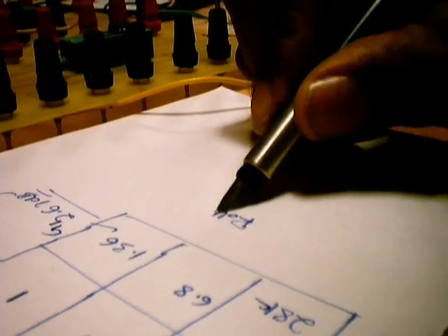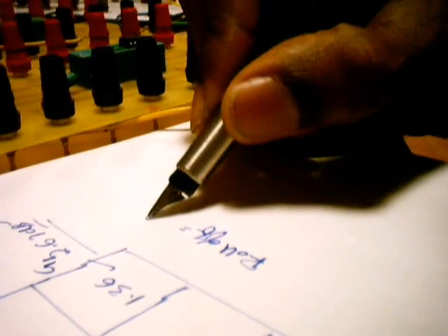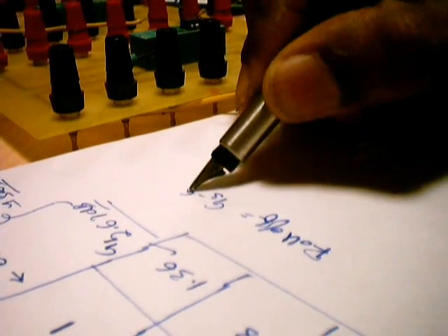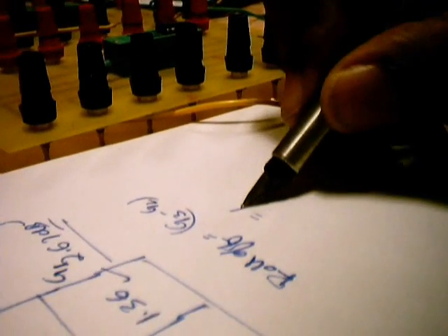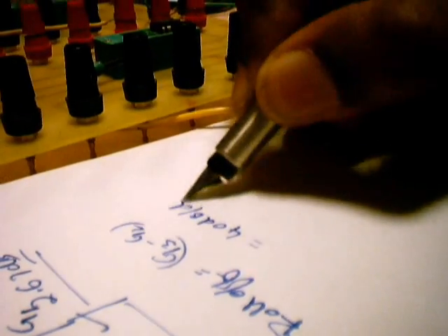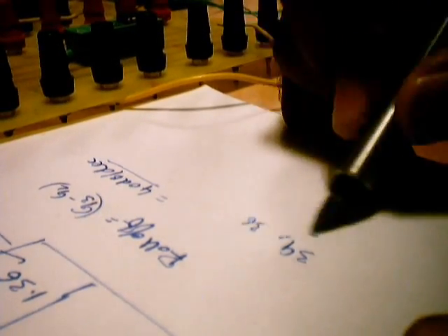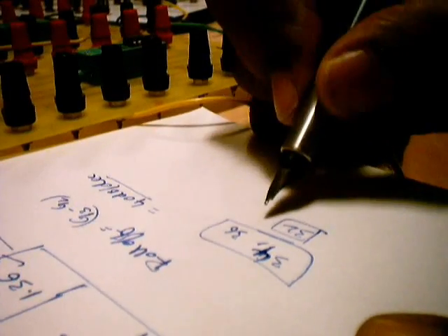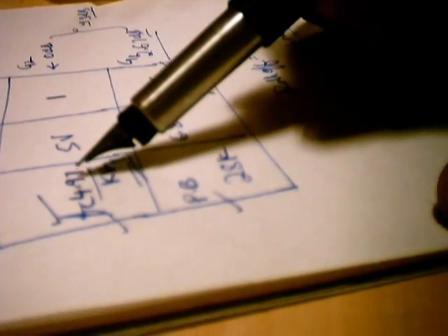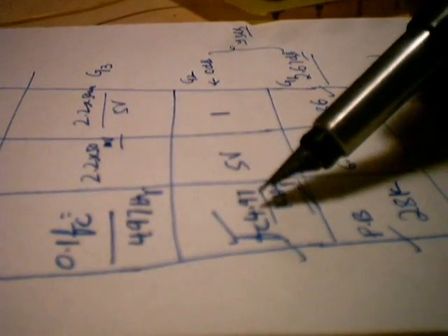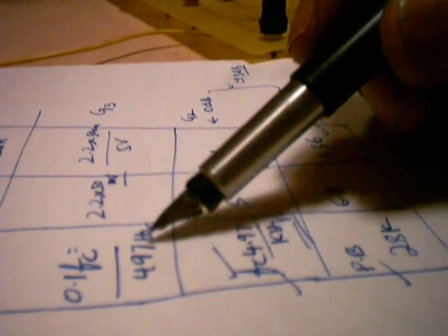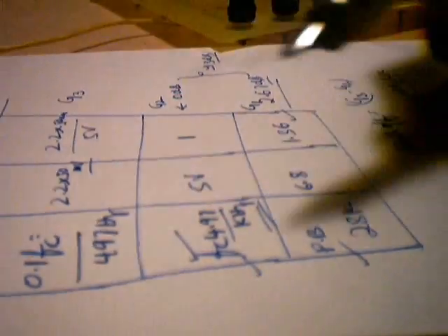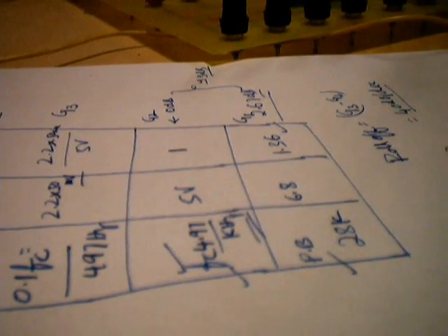The roll off, which is the slope of the filter, you can just take as G3 minus G2, which ideally happens to be plus 40 dB per decade. So we may get a roll off of around 34 to 36, which is an acceptable value. Even if it varies down to 32 dB per decade, it is fine, but ensure that you are changing frequency from 4.97 to 10 times less than that. In this case it was 4.97, that's why we went to 497 hertz. If it was 4.8, go to a frequency which is 10 times less than that, which is 480 hertz.